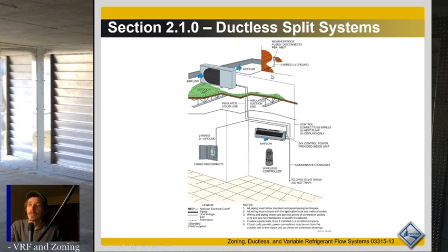Those are very big system losses, which is why it's so important to install ductwork very well, very tight, and insulated. But ductless splits don't have that issue, so that's why, talking residential, our most efficient ducted systems are in the 20 SEER range. Our most efficient mini split or ductless systems are closer to 28, or I think they even hit 30-something now. So all that SEER, all that energy efficiency, is because you don't have duct losses.